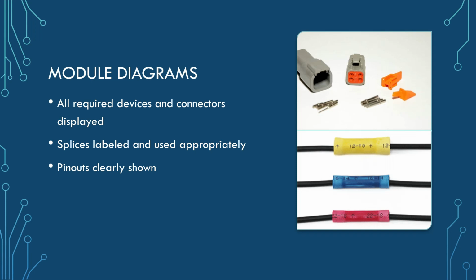Currently, we have 7 modular diagrams: the different sensors that can be clipped on and off whenever they want to, the dash system, power distribution, the main front and rear, a basic power one, as well as steering with all the paddle shifting in the wheel itself. So these modular diagrams make it a lot easier, not just in the manufacturing phase, but in case of emergencies, or in case we don't want to run certain data setups. We can just take that out and switch it with whatever setup we want.